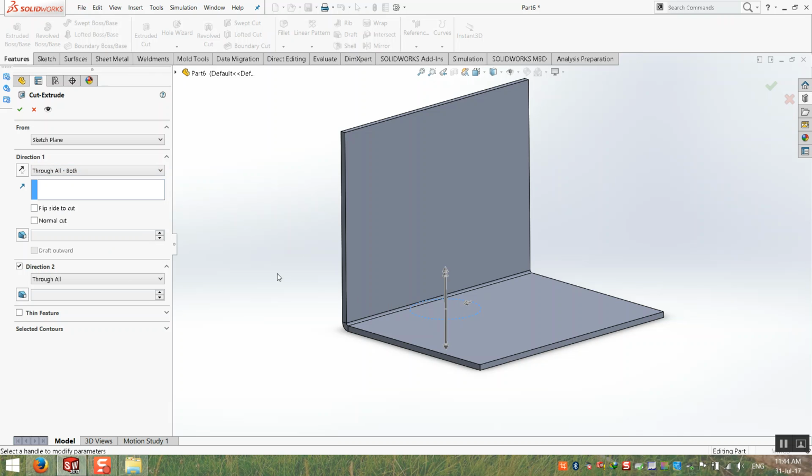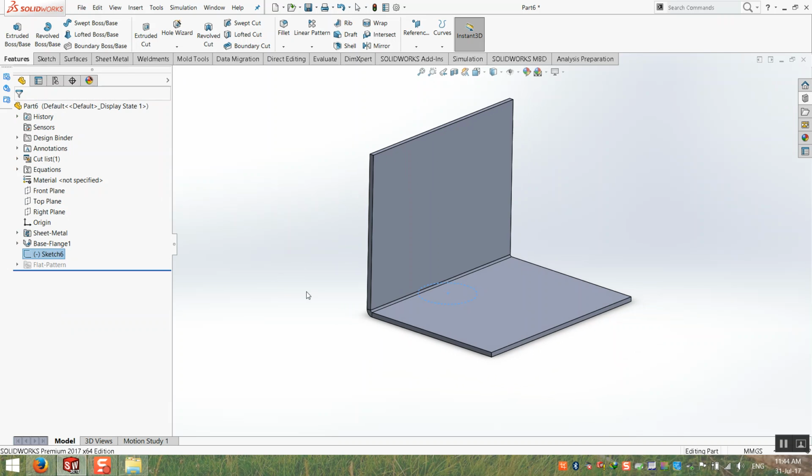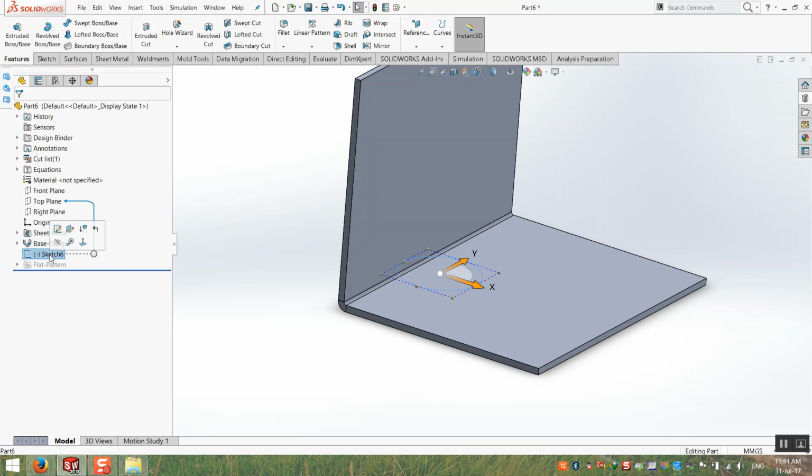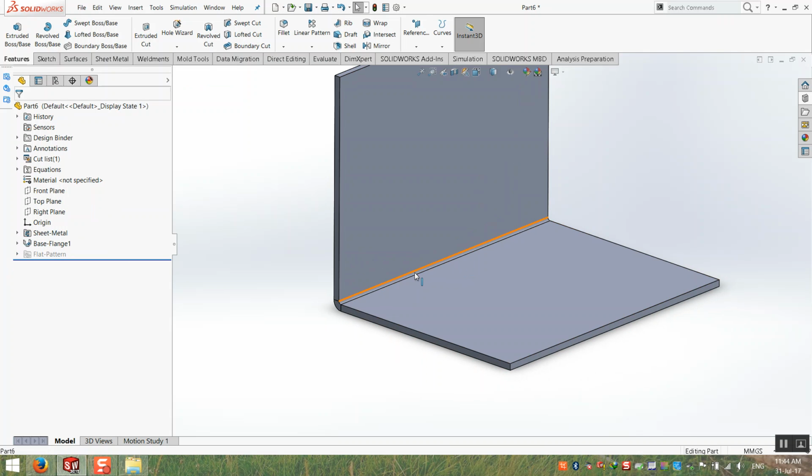So you can do it. Why? Because it's a sheet metal. So you need to cut it before bending. Laser cut. You will cut this circle before bending. After that, go to the press brake and bend the sheet metal.